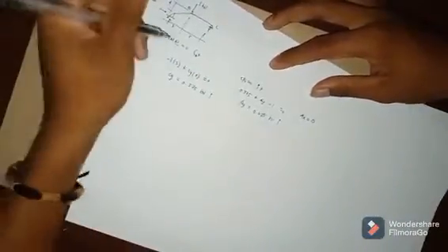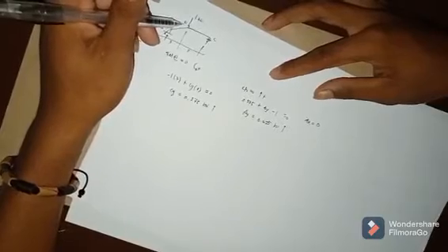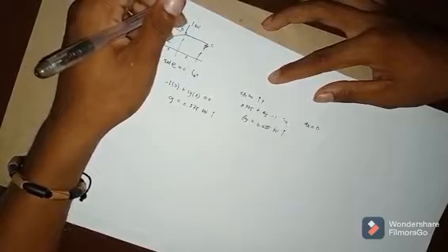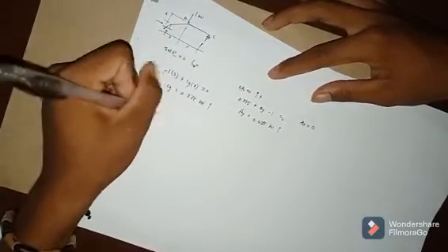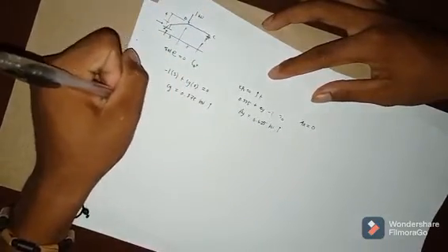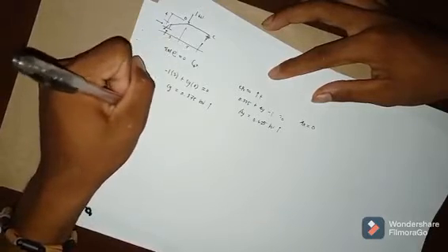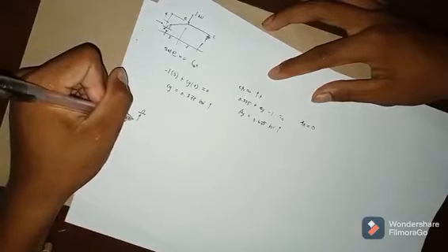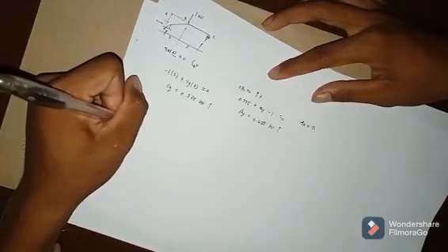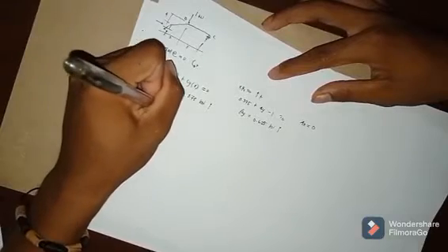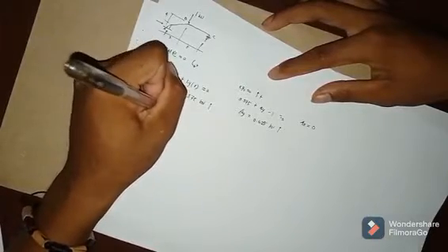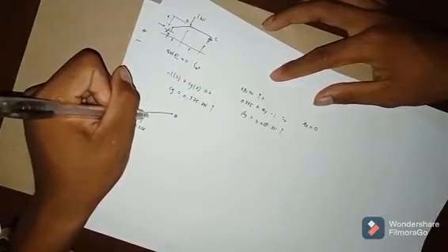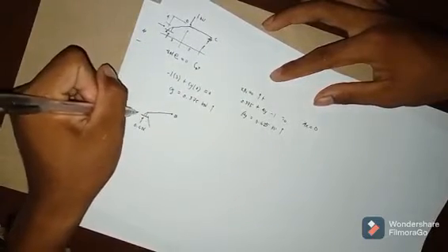So same thing, let's find the deflection here at point B, and considering this area, let's find the moment at A to B. So the reaction is 0.625, and in this area B, to find this, we're going to find the horizontal and the vertical components.